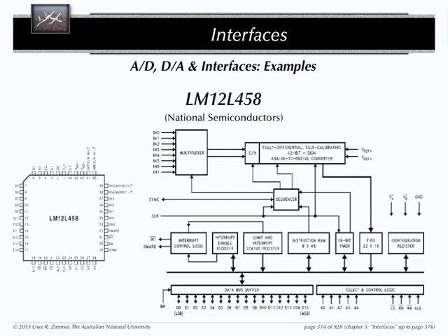So this will not look like a single memory cell to the CPU, but you can select inside this chip 2 to the power of 5 possibilities. Right? So you have 32 possibilities, memory cells to choose from, which are all mapped onto this device. So if you look at it from your CPU, it looks like 32 words in memory.